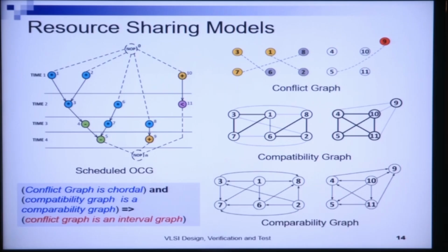Vertices 1 and 7 are non-consecutive, and hence there is a chord joining them in this cycle 1, 3, 7, 6. Similarly, we will see that for all other cycles of length more than 3, I will have a chord joining non-consecutive vertices in the cycle, and hence this compatibility graph that we have here is a chordal graph. Therefore, the minimum clique partitioning problem for this chordal graph can now be solved optimally in polynomial time.